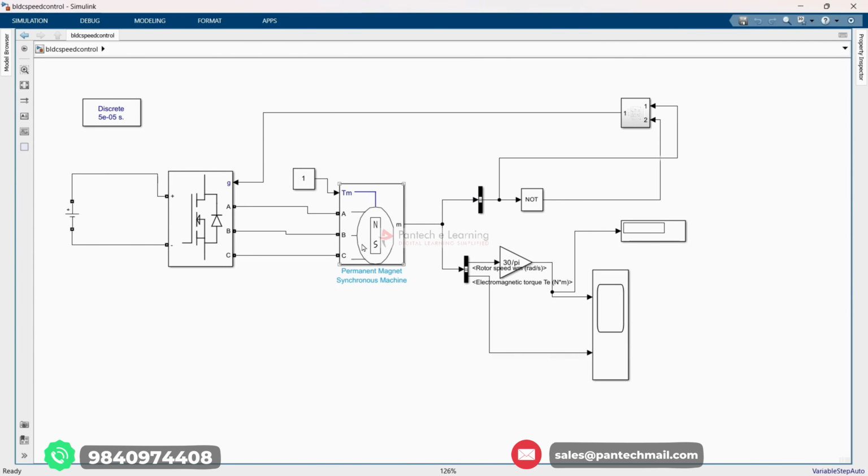So the motor controller uses these Hall sensor outputs to determine the correct sequence for commutating the motor phases. Depending on the combination of the Hall sensor outputs, the controller identifies which motor phase should be energized next to maintain the rotor's rotation. So this is our Hall position sensor feedback given to the motor to rotate the rotor part of the brushless DC motor. Next we are going to enter the speed control methods.